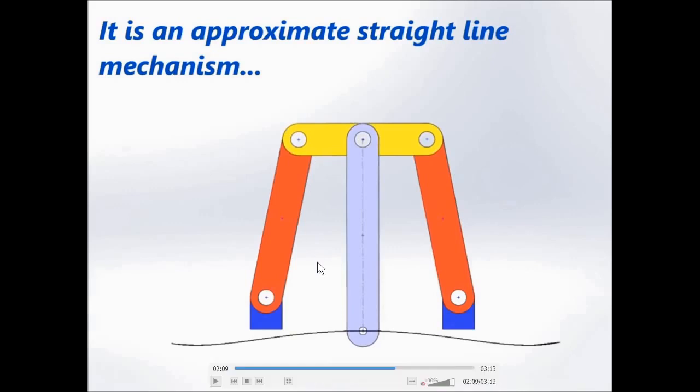That is one condition. So link 1, link 2, link 3, and link 4 all have the same length. Then next is our fixed link and the opposite link, such that the fixed link is double the smaller link. These are the conditions for the Roberts linkage.